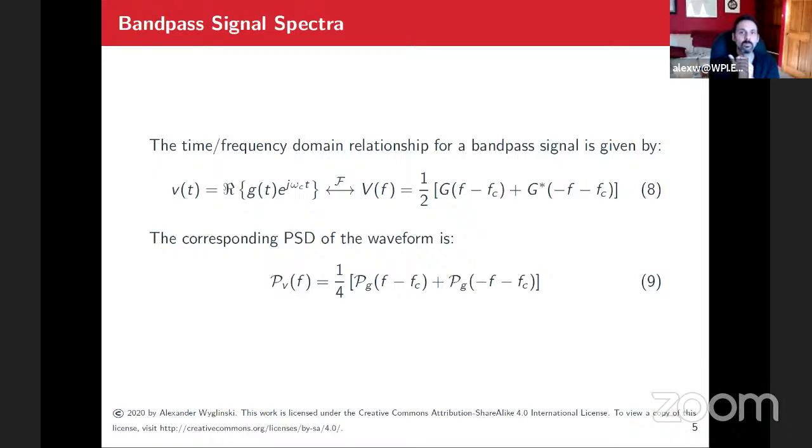Then in the middle of all of that, we're going to look at phase lock loops. So we're going to have all this modulated carrier stuff, but what's going to be critically important is how does the receiver, first of all, track or lock onto those carrier frequencies, right? And is able to say, oh, you're at that frequency, I need to demodulate you back down to baseband.